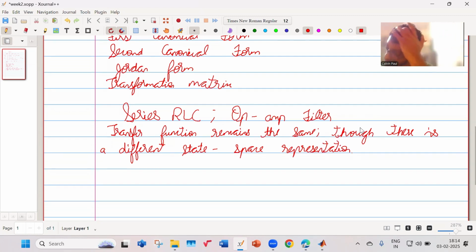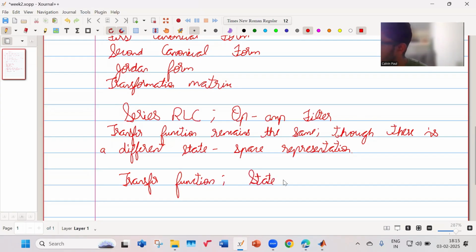Okay, so now, the various things we must consider. Why are we interested in the transfer function? Like we were considering the state vector x, right? Why do we want the representation in terms of transfer function? The reason is that a transfer function is a very well known, understandable way to represent the behavior of a system. Sometimes from one point to another point, the only information about the behavior of the system is a transfer function. So how do we convert